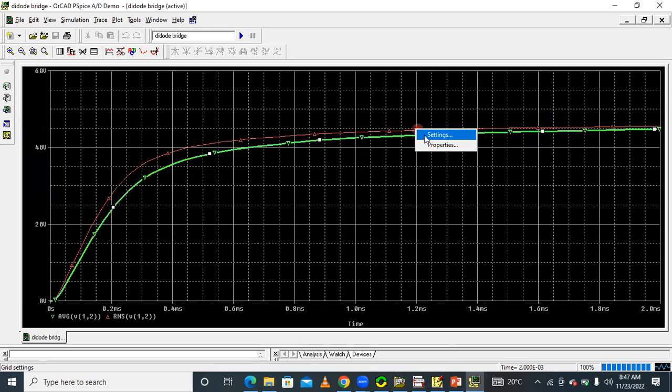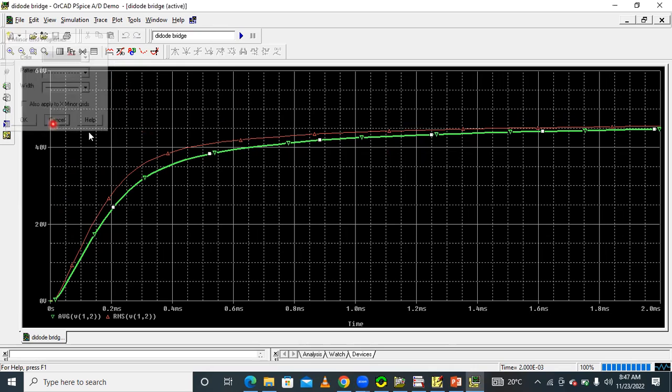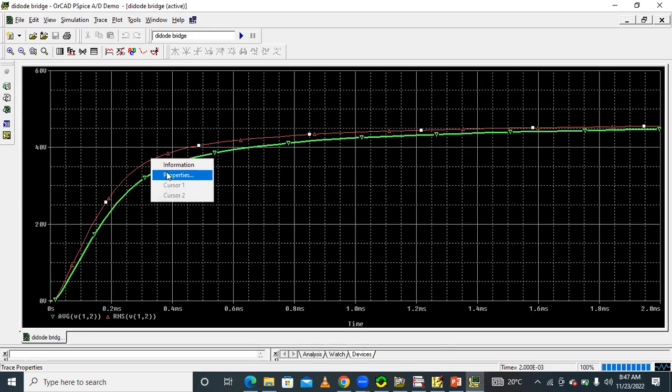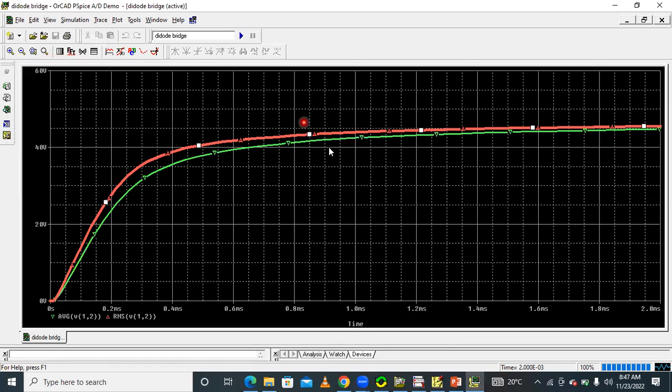These are the properties entries, and this is the RMS value. This is the way we have to execute. By increasing the capacitor, the ripples are reduced to very little. The RMS value and average value are approximately equal. So this is about the single phase diode bridge rectifier.